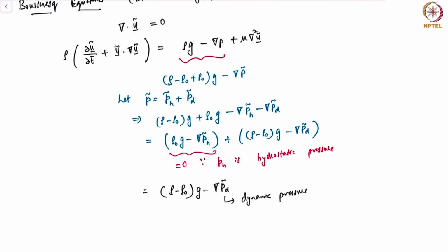Okay. Now in the Boussinesq approximation, what we do is we say that the density variations are only important in the gravity term and in no other term. So one can systematically expand, for example, in the inertial terms you have density rho. This rho can also be thought of as some mean value rho naught. Let me write that down. So in the inertial term you can say that it is rho naught plus a delta rho, that is the fluctuation of the density.